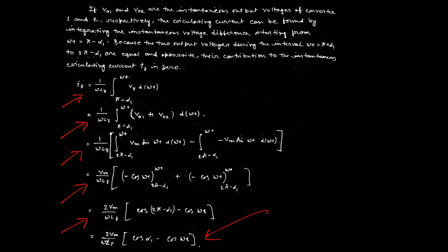So the total circulating mode operation, inverting mode operation or rectifier mode operation depends on this particular value alpha 1. Now consider alpha 1 equal to 180 degrees. Then the first converter starts working. If alpha 1 equals, suppose, 0 degrees, then the second converter starts working. If alpha 1 varies from 0 to pi by 2, then the first converter can provide the positive current.